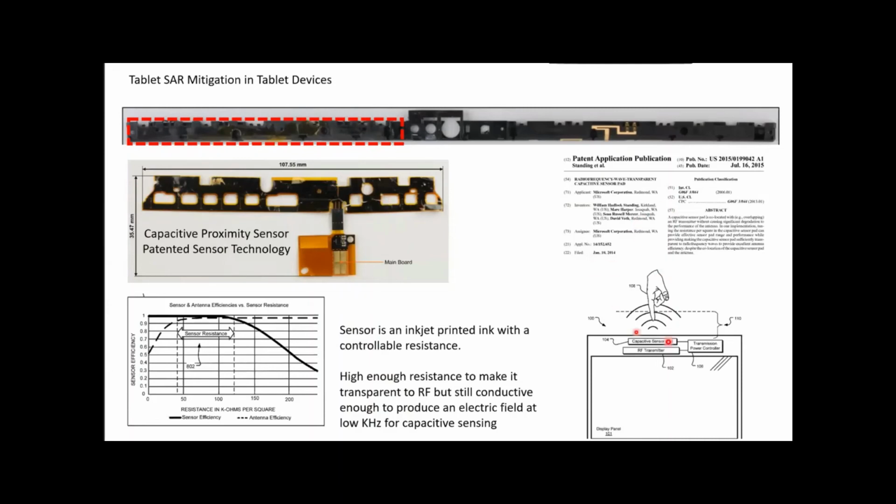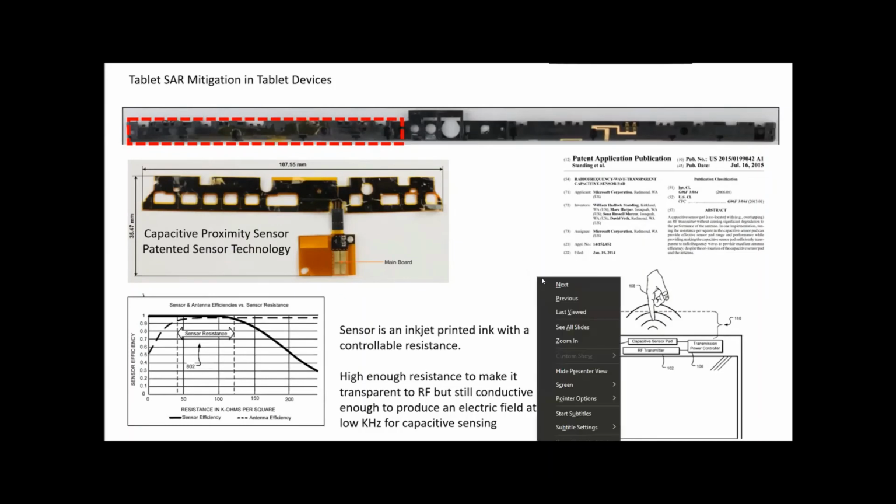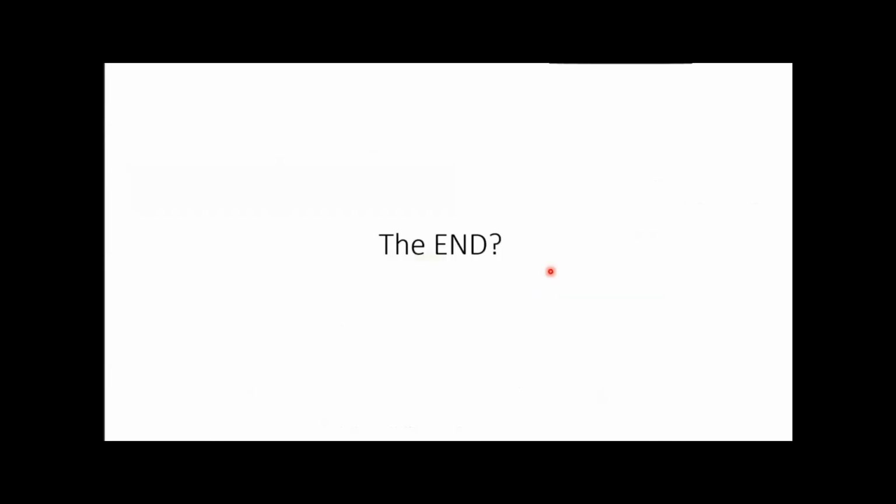And what happens is, as you can see in this diagram here, if a hand is coming close to this sensor, then you're basically measuring the capacitance difference between this plate and my hand using the oscillator, and that basically gives you a change of capacitance. And that's effectively how we know there's an object that's probably a human next to us. So with that, I will end the presentation, and thank you very much.